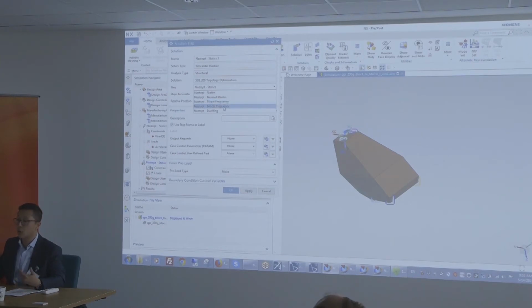But we can also do modal frequency. So solution 111 in Simcenter Nastran to apply a PSD directly. Okay. We can also have a buckling step, and more. Right now we're adding more subcases. So all the subcases you've seen when I looked at the solution, those are gradually being mapped into the product.